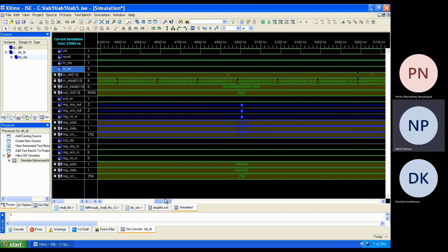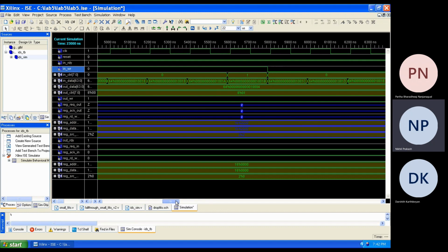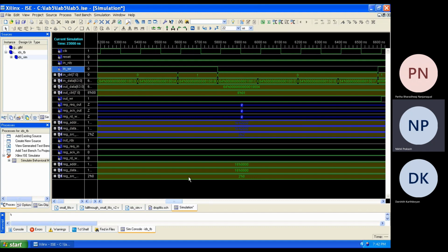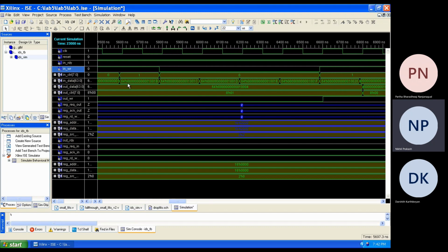So when we forward the simulation, we get to see here that we have received the end word of the entire data packet. Probably in two to three clock cycles, because we have a lot of flip-flops there, we should see the data coming, because by then we would have done the pattern matching for every word in the packet, and we would have the result ready.